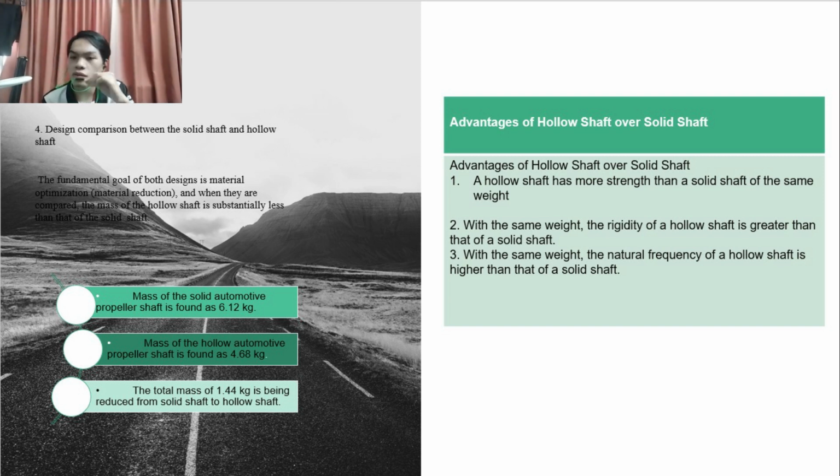So, advantages of the hollow shaft over the solid shaft. Advantage number 1, the hollow shaft has more strength than the solid shaft for the same weight. Number 2, with the same weight, the rigidity of a hollow shaft is greater than that of the solid shaft. Number 3, with the same weight, the natural frequency of a hollow shaft is higher than that of the solid shaft.